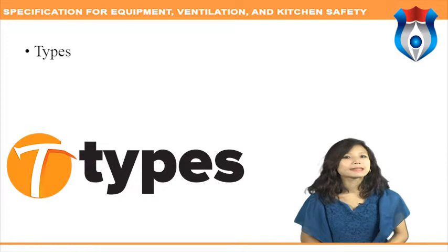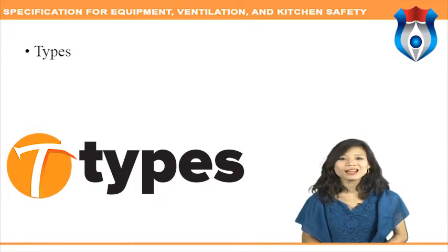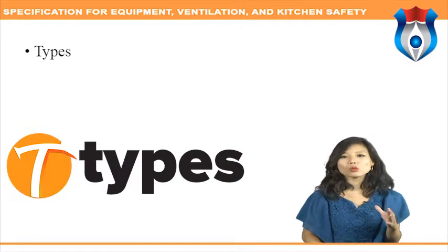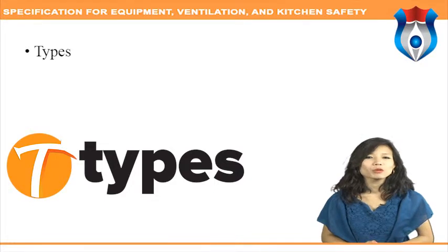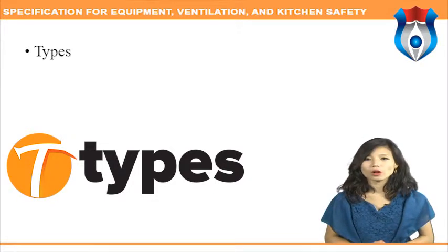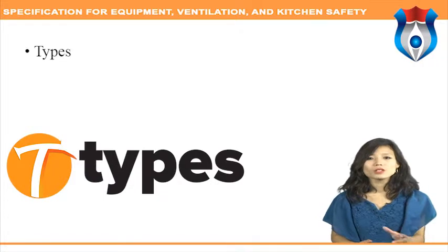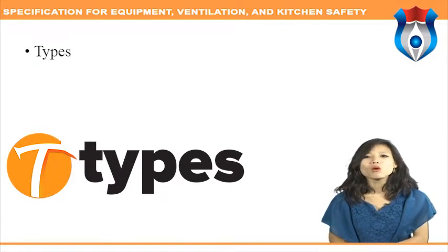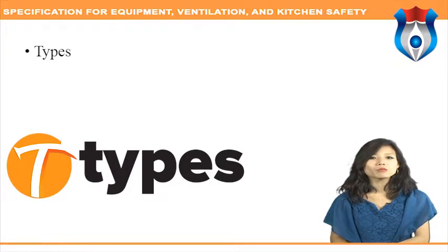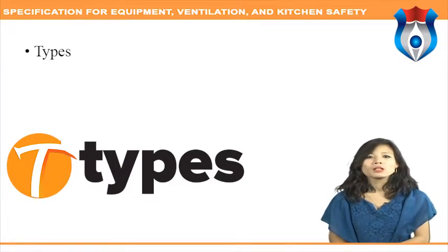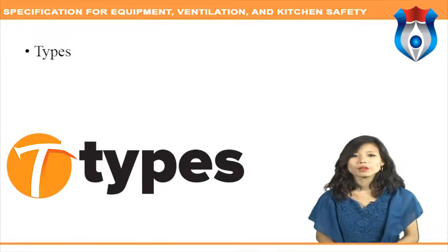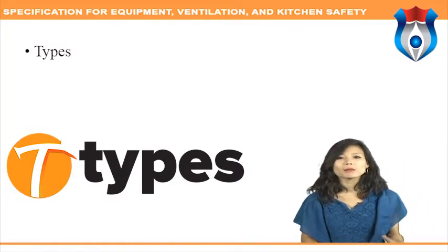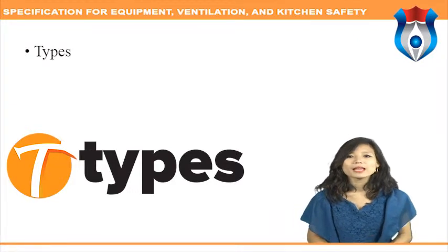These stainless steel sheets are produced in India according to the standards of the Steel Authority of India that controls the amount of alloying material. The corrosion resistance of stainless steel is attributed to the addition of chromium to the alloy. Nickel lowers the thermal conductivity of the alloy and increases its coefficient of expansion, allowing it to be formed into various shapes more easily. The amount of carbon is restricted so that the alloy can be welded without forming chromium carbide, which lowers corrosion resistance. Stainless steel is produced in sheets, plates, bars, wires, pipes and tubing.